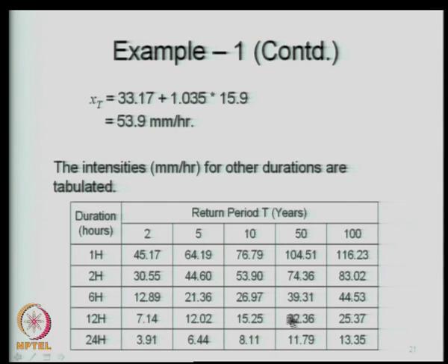What does this table give? This gives in fact the IDF relationship. These are the intensity values, these are the durations, and these are the return periods or the frequencies. So, this table thus gives the complete IDF relationship. Typically, the IDF relationships are shown in the form of curves.